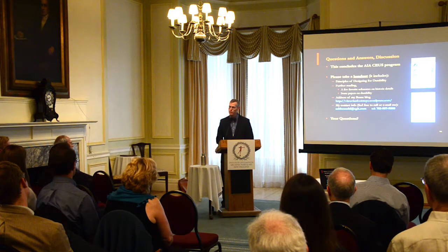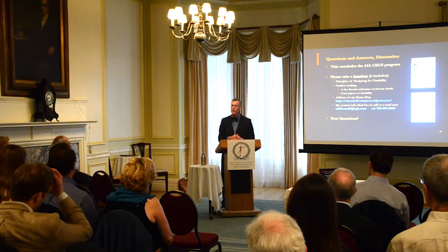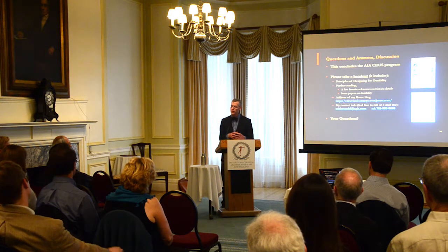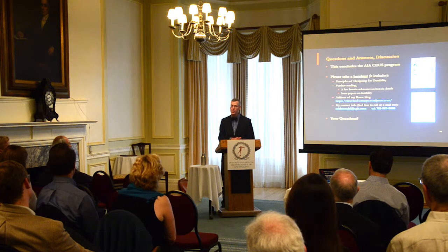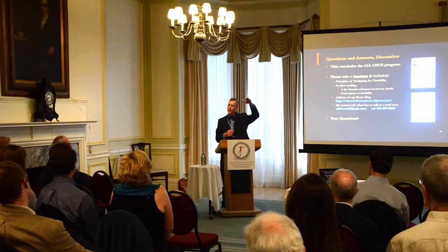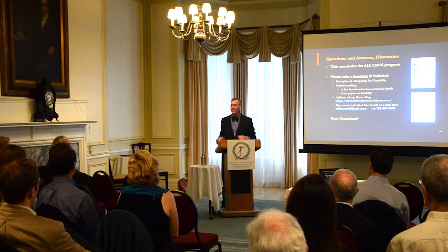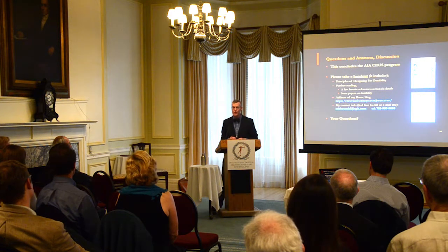It's not as obviously recognizable as contemporary concrete because they used very large aggregate, typically baseball or softball size. Sometimes they used chunks of stone for that, and sometimes chunks of brick. In the case of the Pantheon, there's a very clever design where the higher they got on the dome, the lighter the aggregate they used, to help deal with the structural forces on that dome. So they were using things like pumice, which is very light, for the aggregate higher up, and transitioning.